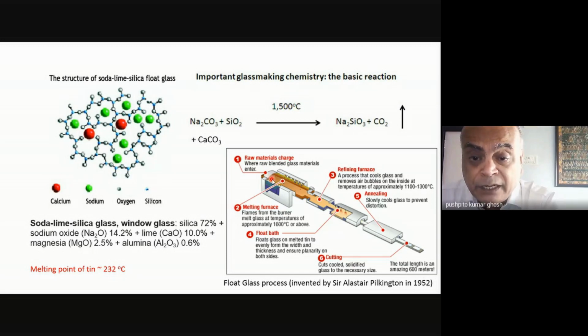First, you will melt the glass in a melting furnace. We are talking about the soda lime type of glass, which is also known as window glass. And this is typically the composition. All of this, as I told you, is silica, and inside it you will find the impurities of calcium oxide, sodium oxide, alumina, MgO. All of these things will be sitting in it, and that's what actually distorts the structure and lowers the melting point. We said that glass will melt around maybe 1000 degrees or a bit less or a bit more, depending on the composition.